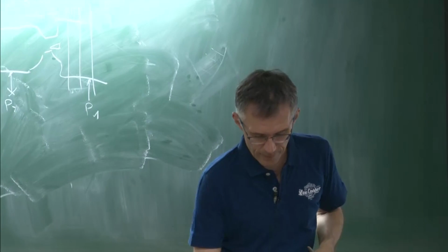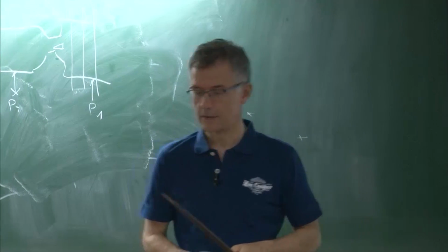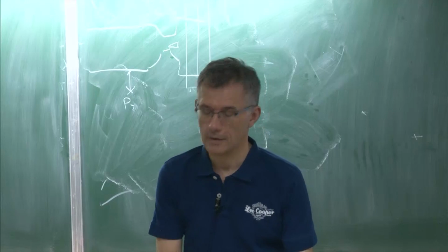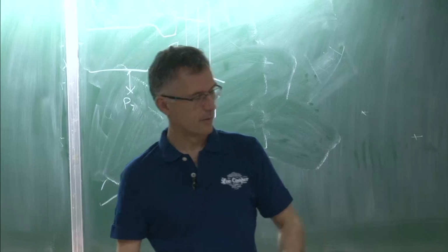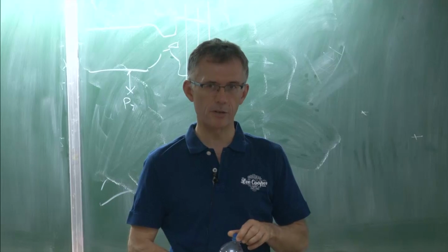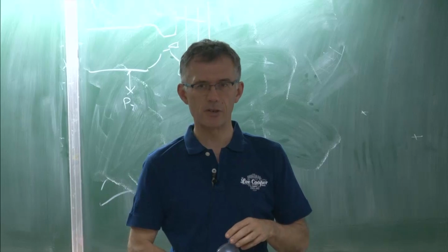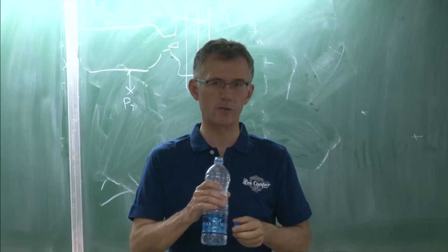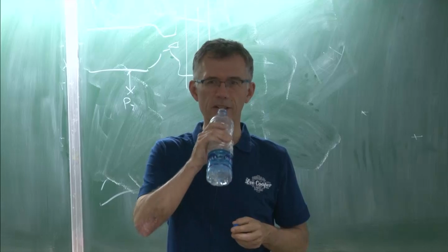Okay. So, have you ever tried running LES on diffusers? Were you able to predict the pressure loss? Not on diffusers. Diffusers are tough, because you get separation. Well, it depends. If you have separation, then it's really the outlet boundary condition which you need to work on. We didn't do it on diffusers. But that would be an interesting one, yeah.